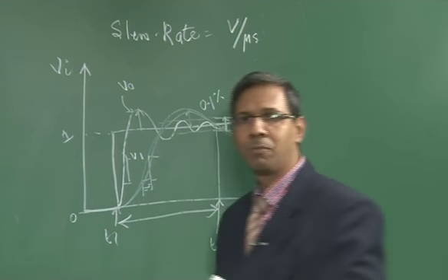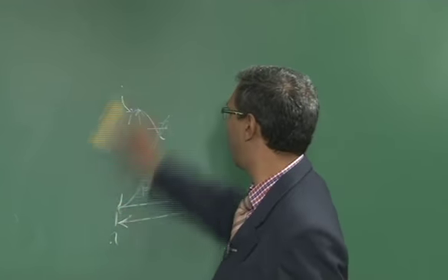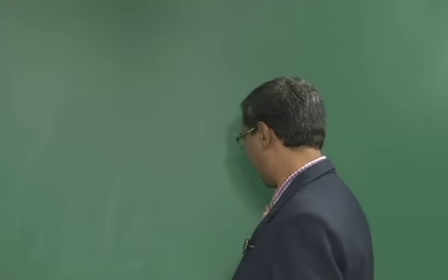Now with this we can move on to the other type of parameters. This one has more to do with the transient phenomenon. Now let us look at two things. The input impedance and the output impedance were already seen in the op amp model. We saw the practical op amp model wherein we showed Ri as the input impedance, which is the impedance between the two input terminals, and we also displayed R0, shown in series with the voltage gain block AD times VD, which is the difference of Vi and Vni.